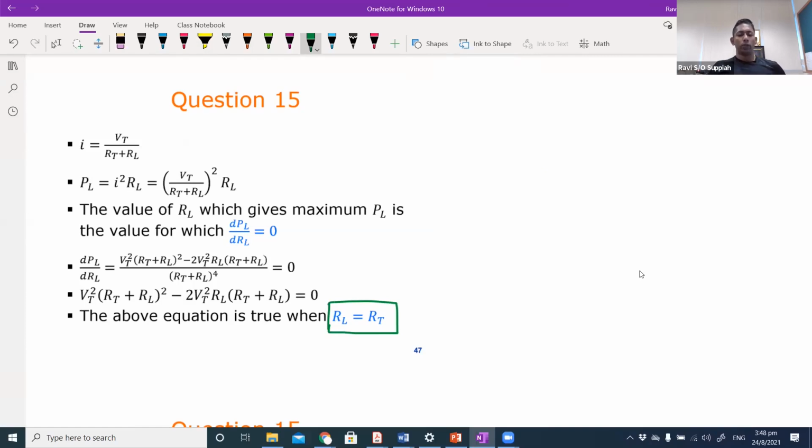So when you derive the final Thevenin equivalent circuit, what it tells us is very important because it gives us the Thevenin equivalent resistance. That means when I know the Thevenin resistance, I must find a load with a matching resistance. Then I am sure that the maximum power will be delivered. If my load does not have a matching resistance, it will still work, but I will not get the maximum power delivered to the load. That means I might waste a lot of power within the internal resistance, the Thevenin resistance.